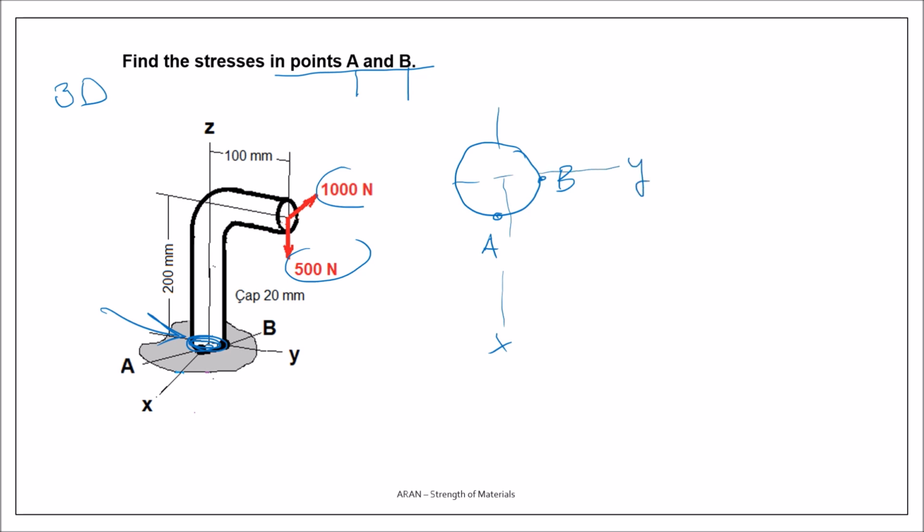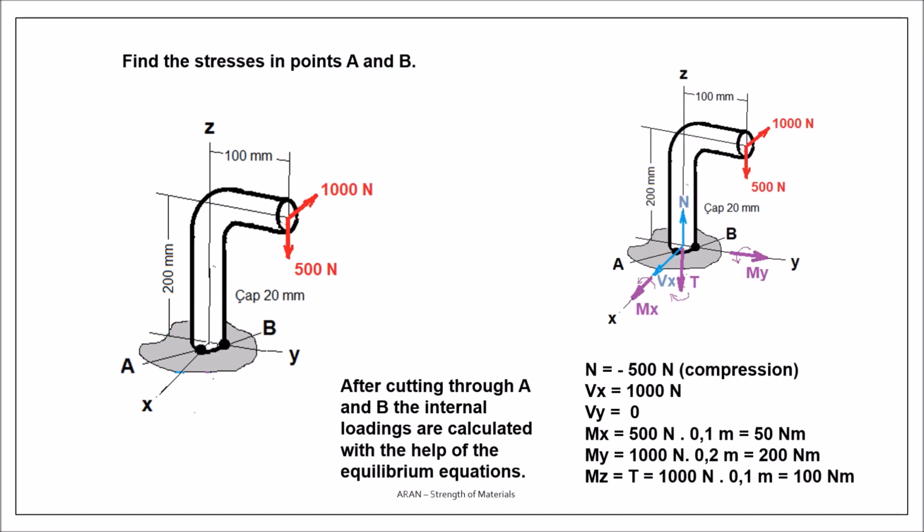So I have to find the moments and the forces in this section. When you cut, you see, you have to find each force one by one. Well, if you look at the whole drawing, you may think it's too complicated, but it is not. After cutting through A and B, the internal loadings can be calculated.